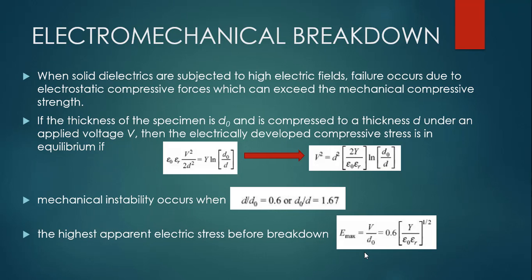Now recently this theory has been modified based on the concept of fracture mechanics. In the new mechanism, filamentary shaped cracks propagate through the dielectric material, releasing both electrostatic energy and electromechanical strain energy stored in the material due to the applied electric field. So this was the previous equation that governed this kind of mechanism, but recently we have the concept of fracture mechanics, where there are filamentary shaped cracks inside the insulators.